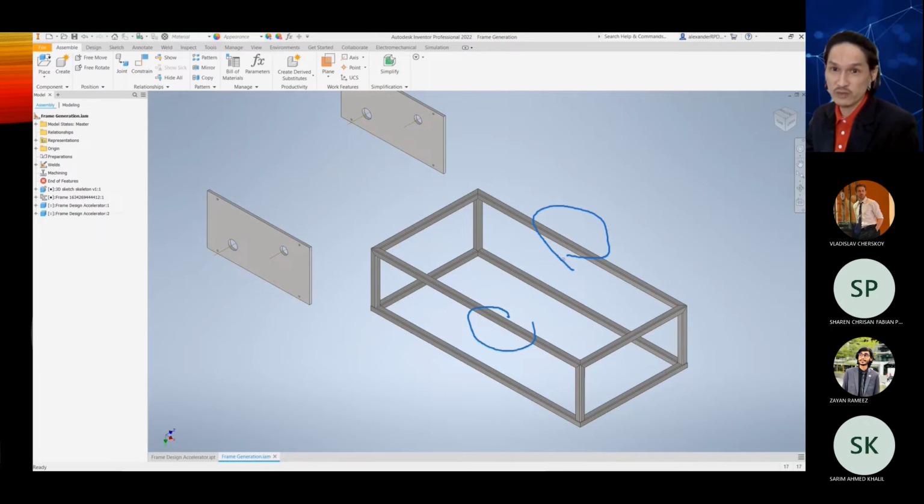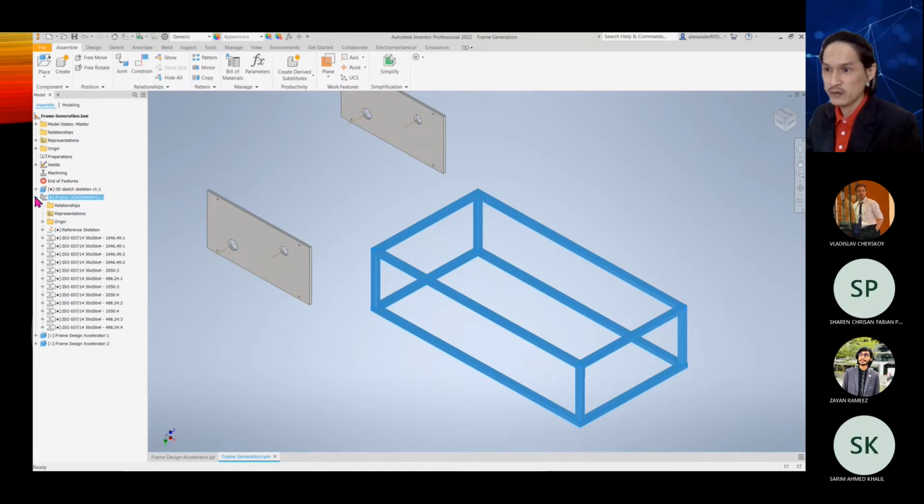To drill a hole on the frame is very common, right? So that's why we need to know how to do that. But all my frame is grouped under this features tree. So I open it, you don't know which one is which. But when you just move your mouse there, basically you will know. Just move your mouse, no need to click. So now I would like to have that frame.